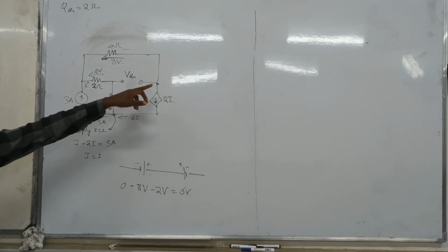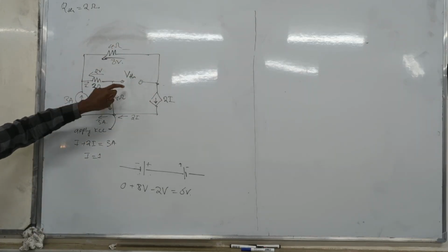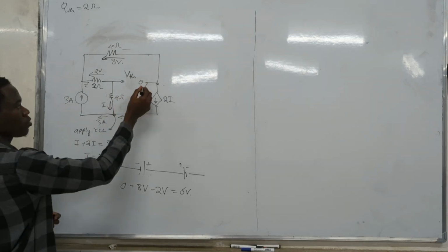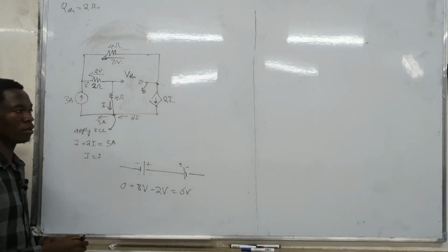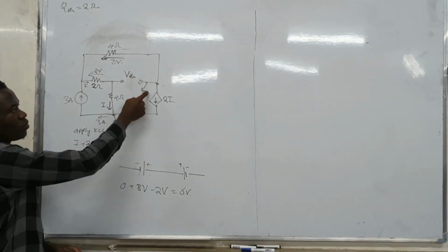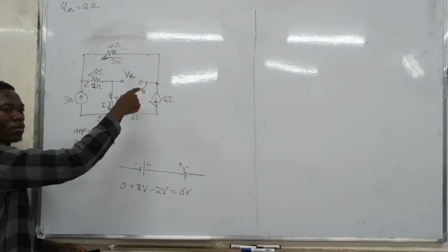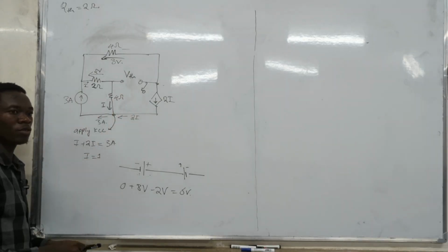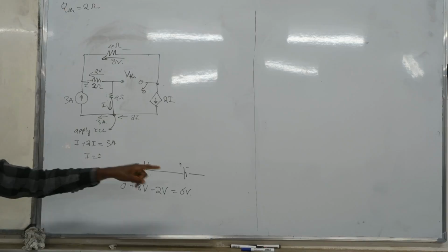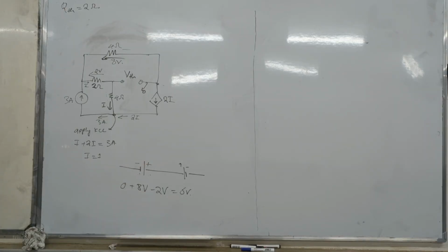So meaning we've moved from this point to the other point. So what's the voltage difference? We assumed this as 0, so it's 6 minus 0. You get 6. So when you assume this as 0, just walk around the loop, you get your voltage. You can assume it as 5, and when you do that, you find the difference, you still get 6.